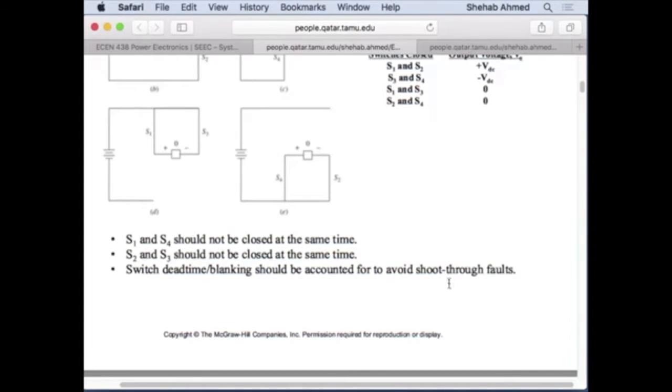And if you look at our representation of the combination of 2 switches as a single pole double throw, this arm that oscillates between these 2 points is a good way to think of that, right? It takes time for this arm to move from one point to the other. This time is dead time, right? Why do you need it? Because you don't want to cause a short circuit across your supply.